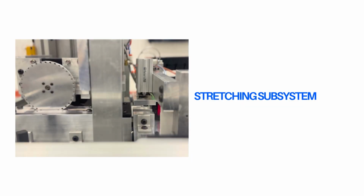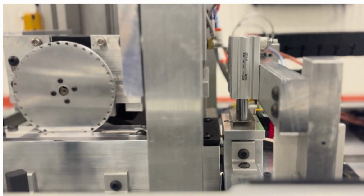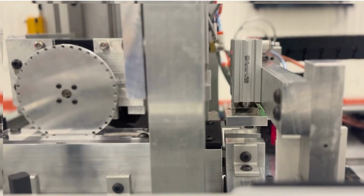Stretching subsystem. Once clamped, an electric IAI linear servo motor pulls the grip assembly along the dual linear rails to achieve the exact target length of 5.5 inches. The static friction and the back pressure provided by the in-feed wheel and channel maintain constant control of tension throughout the stretch.